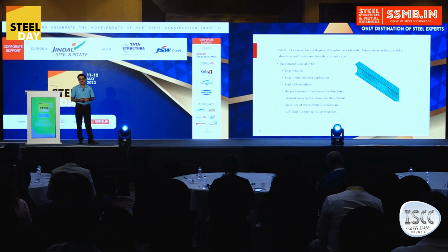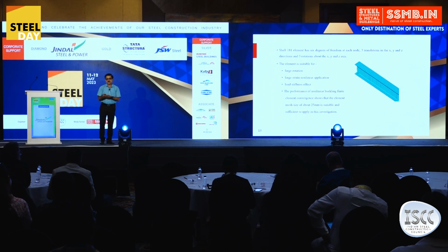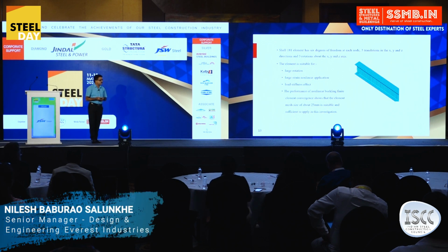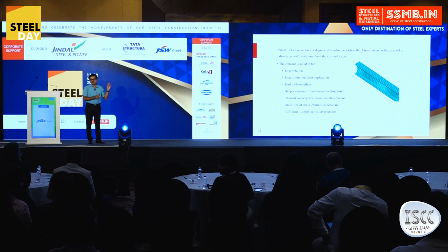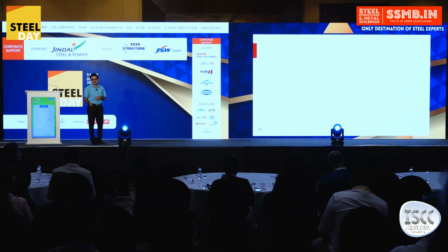Shell 181 element has been used for this particular analysis, which is suitable for large rotation cases and large nonlinear applications. The convergence of the nonlinear buckling finite element analysis was tested, and it was found that a 25 mm element size was suitable for this analysis. For solving the nonlinear problem, the Newton-Raphson iterative method was used, and some 2-3 points were mentioned to explain what the Newton-Raphson iterative method is.